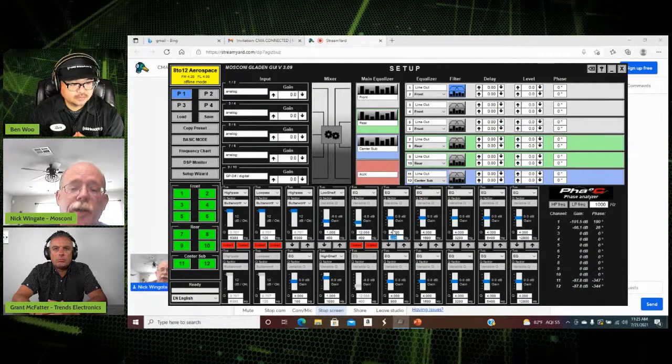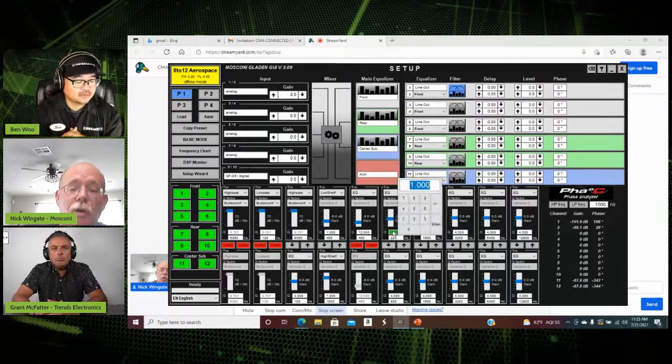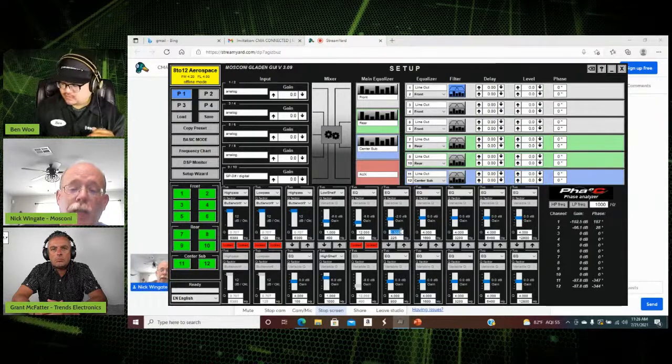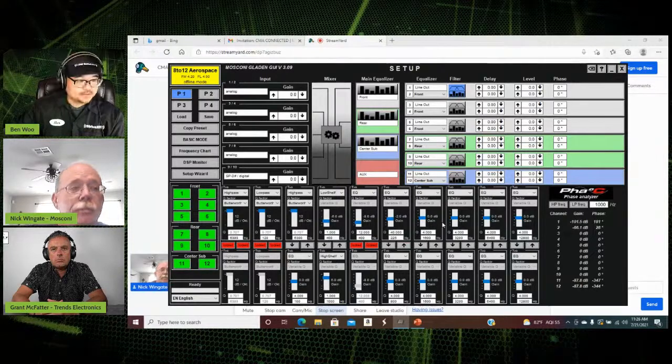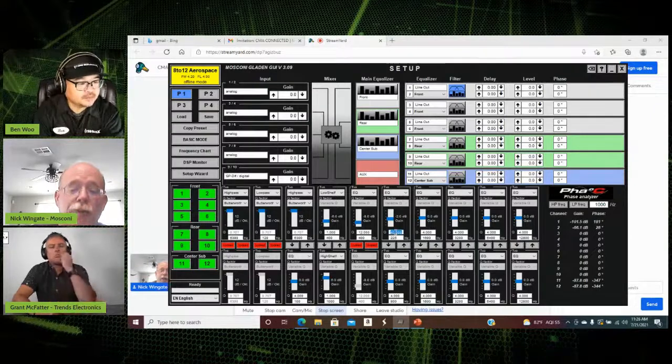But I don't want it to be just 220 hertz or just a little bit either side of it. So I'm going to do a Q of 1, which means that I'm now affecting an octave. At 1, it's wide enough to affect the entire octave. Exactly. I can do a Q of 0.5, which is extremely wide, or I can do a Q of 40, which is the exact frequency. And I can do it anywhere in between. I can type in 39.5 here if I wanted to.